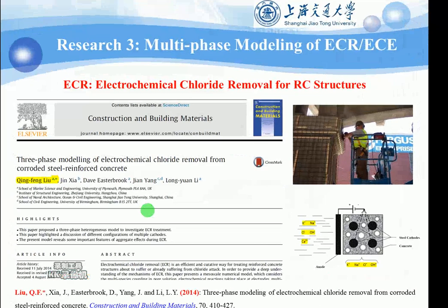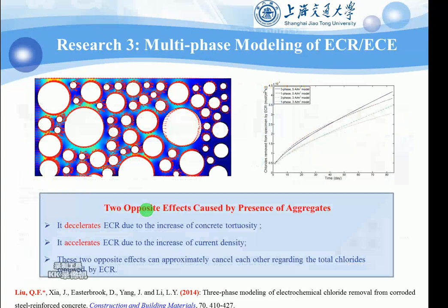So after about two studies on transport phenomena, we started to use this model to simulate the ECR treatment, the repair method for concrete structures about to suffer or already suffering from chloride attack. In this study, the most interesting finding in my eyes is that the presence of aggregates causes two opposite effects on ECR.